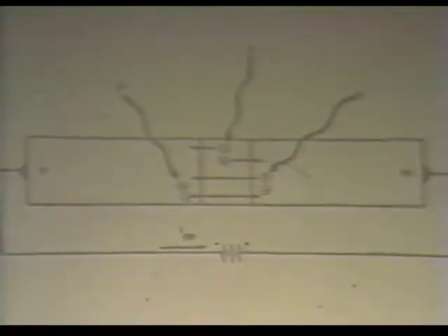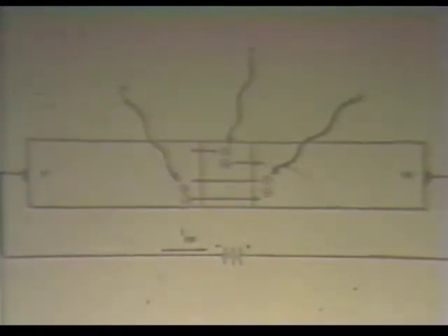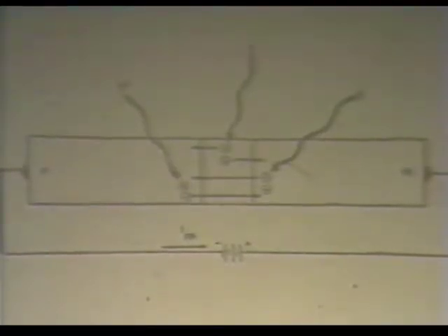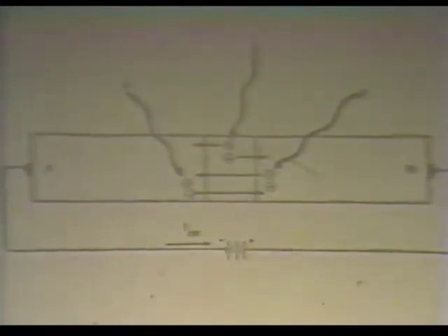You know, they must have. I've got charge carriers here. How did they get here if they didn't turn me on? So it acts just like you turned it on. And it puts a big pulse of current that we call photocurrent through that diode, even though it may be turned off in reverse bias to create your depletion volume. It acts just like it's turned on. And zap, a big pulse of current goes right through it.